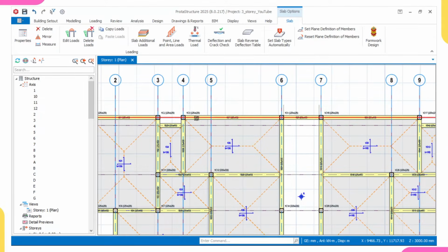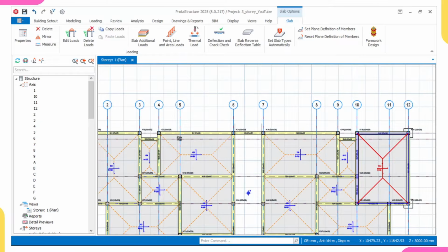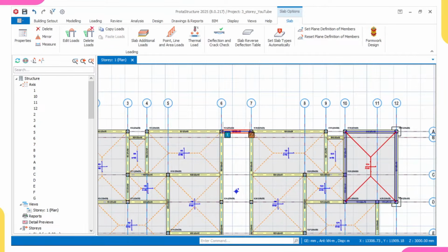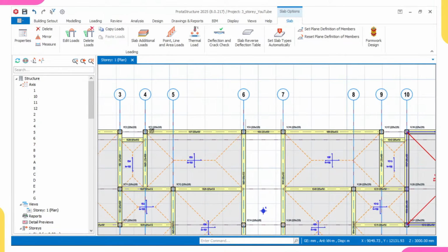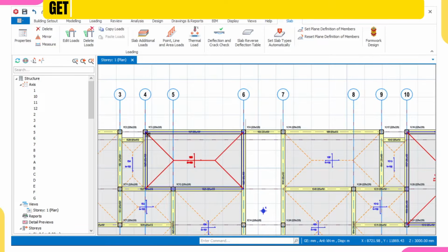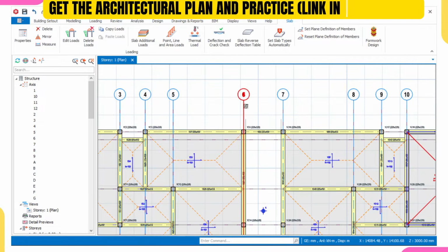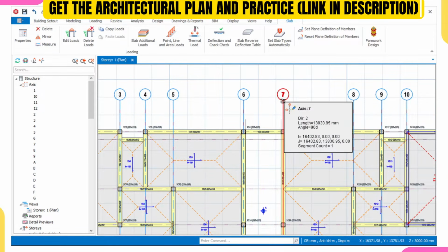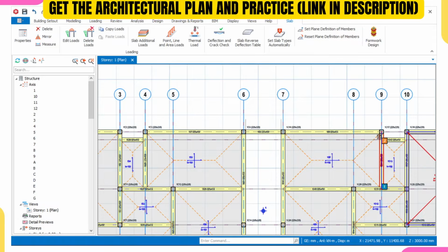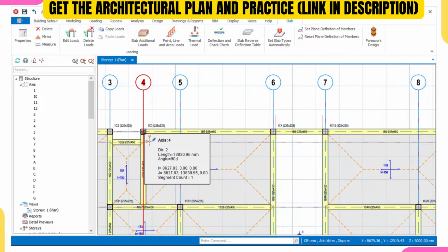Okay, let me explain. You know that summation of moment. I'll explain using this beam. If I want to draw the bending moment diagram of this, look at it. It will go like this. From this point, it will go up like this, come down, go up because of this hogging moment, come down because of sagging moment, then terminate at this. If you see now, it started from here because the moment at this point